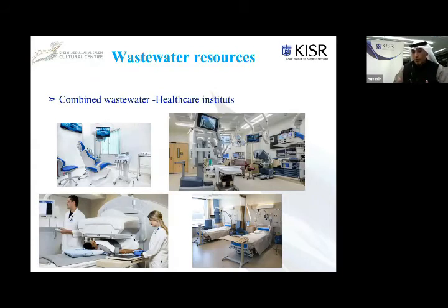So what we mean by combined is that the wastewater generated from those healthcare institutes is mixing both municipal and industrial wastewater related to the activities, and it has to be treated separately before it goes to the sewer network. Of course, the problem here in Kuwait is that the hospital is connected to the Ministry of Public Works network, and they are directly shifted to the municipal wastewater treatment plant.